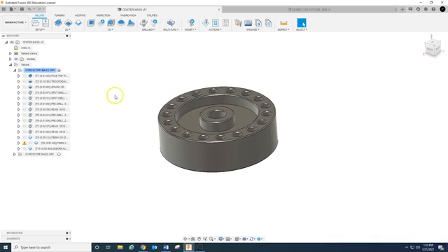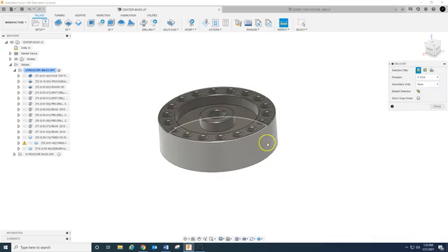So our material for this project is 3.5 inches in diameter. And I'm going to check this. You see my diameter of my model is 3.375. That means that we have a 1/16 inch on each side that we're going to be able to cut off, an 1/8 inch total.